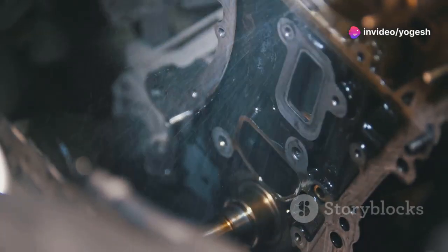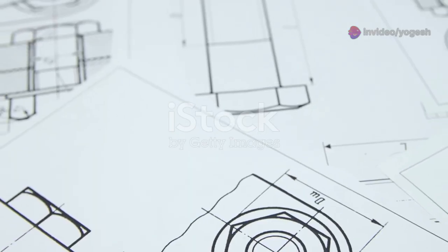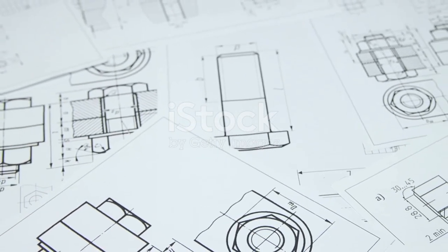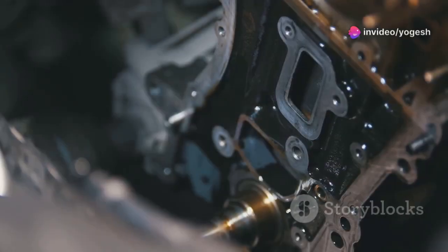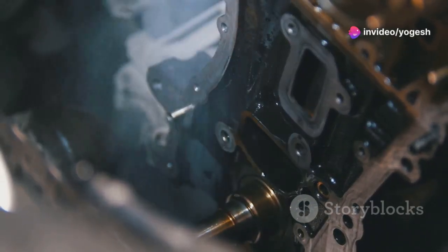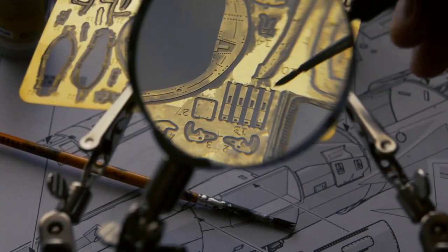Break lines let you shorten long, uniform parts on your drawing. Use a thick, wavy line for small parts, or a thin, zigzagged line for large ones. Always show the true length with a broken dimension line. Only use break lines if the cross-section is constant. Don't hide features in the middle. Break lines save space and keep your drawing readable.